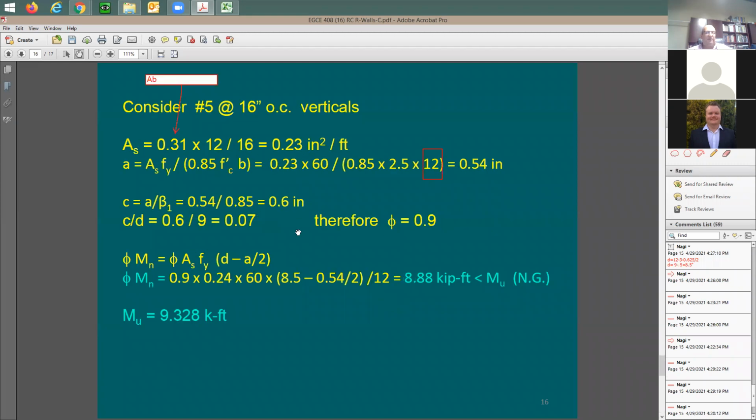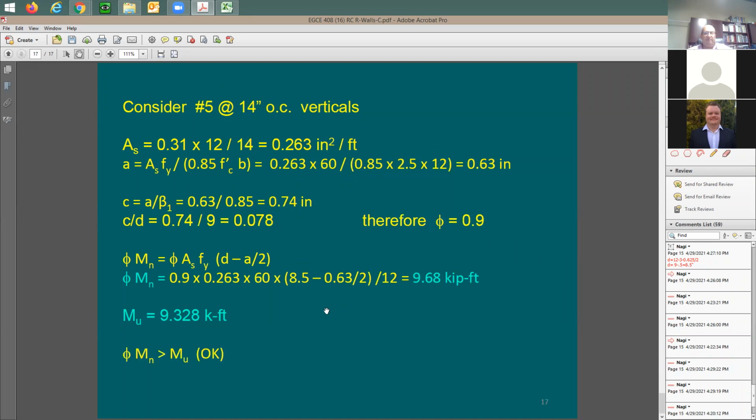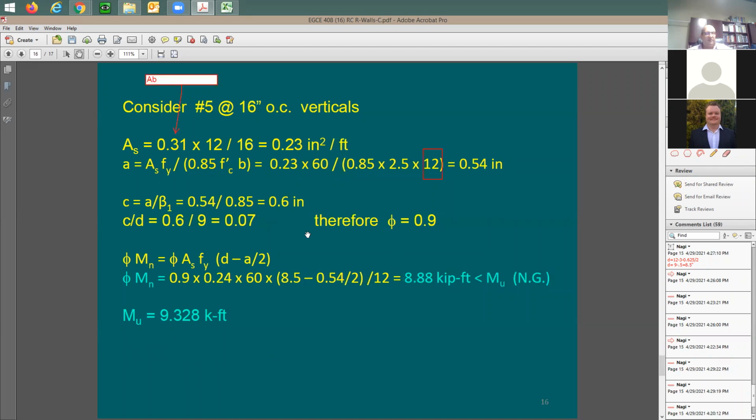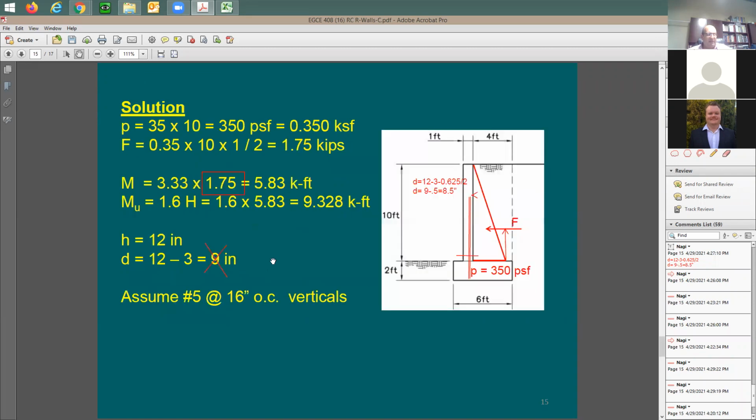And then after that, you're going to be doing AS. So this part here, you have done it a few times, many times by now, right? Design of a rectangular section for some moment. So the only thing that is going to be a little bit different is going to be this trick here. If I give you the soil pressure, can you find out the ultimate moment on the wall section? All right, any question?